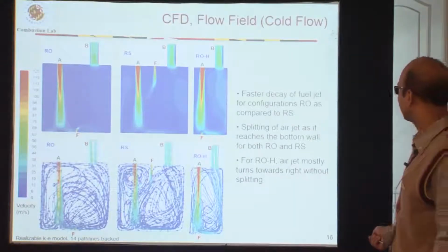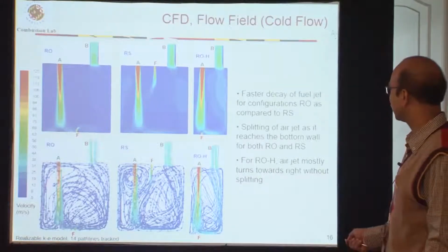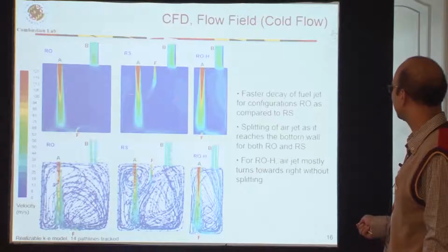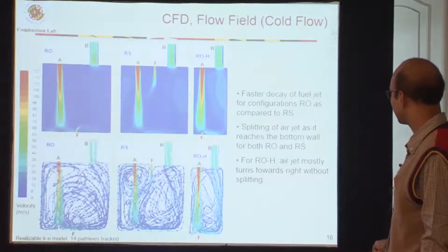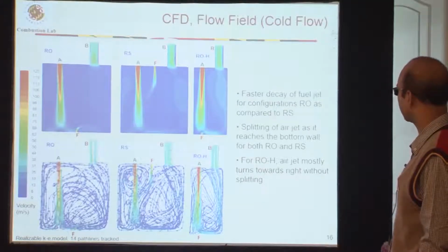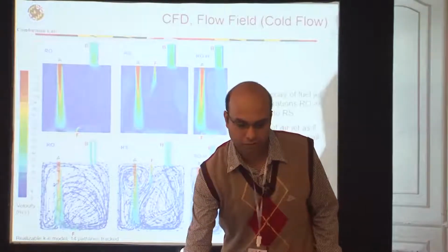and we also observed that this cannot sustain reactions. One thing to do is to eliminate this recirculation. We can reduce this dimension, and if I reduce this dimension, then I observed that most of the gases are recirculating from the right. So possibly that will be more beneficial.